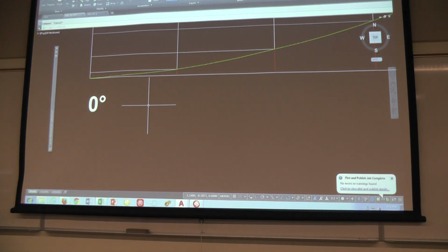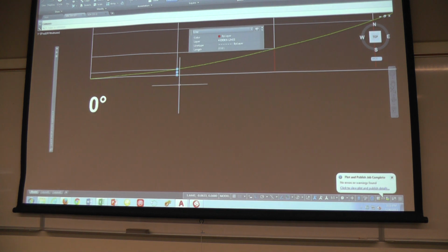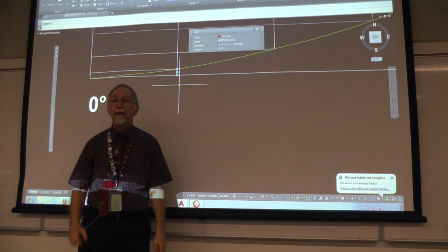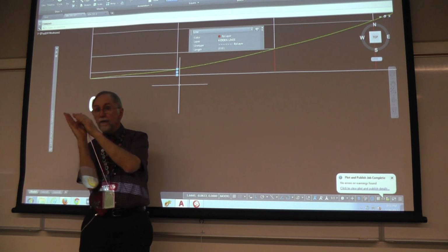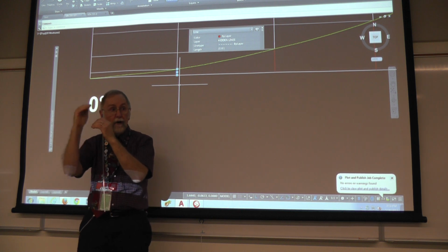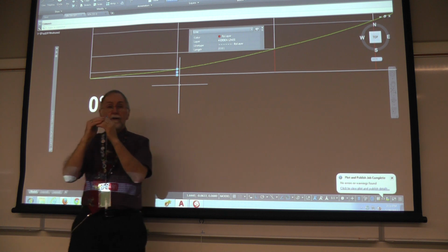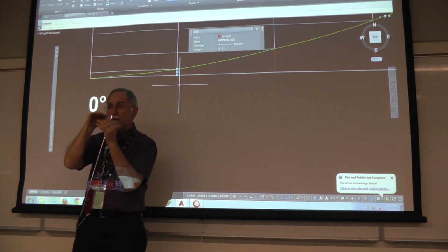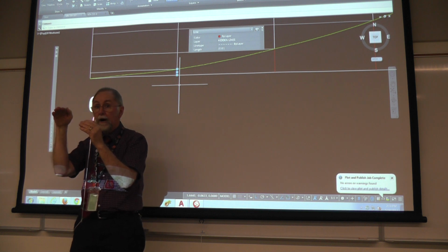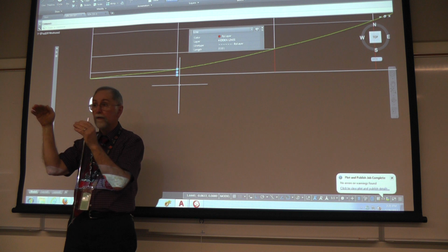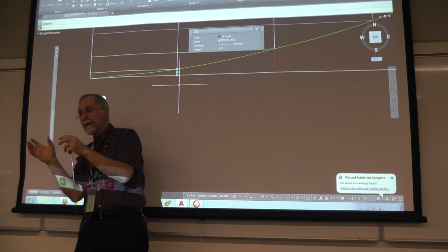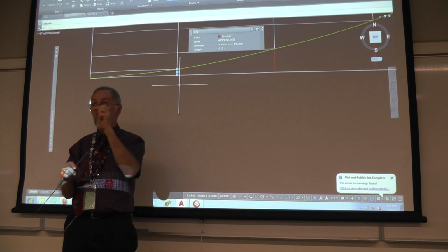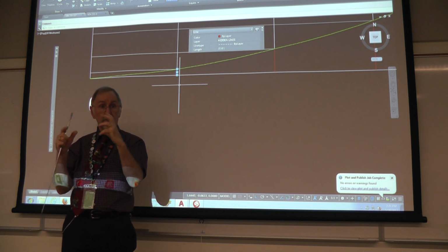So I'm going to go over here, and I'm going to click on it with my quick properties on, and I'm going to find that it is 0.0381 in length. That means at the 18-degree increment, the cam follower has to move out from the prime circle 0.0381. So the bottom of the edge starts at 0, and then the bottom edge of that cam follower is going to go out beyond that by 0.0381. Okay, that makes placing that cam follower diameter a little more difficult than if I use the center of the cam follower as a starting point.